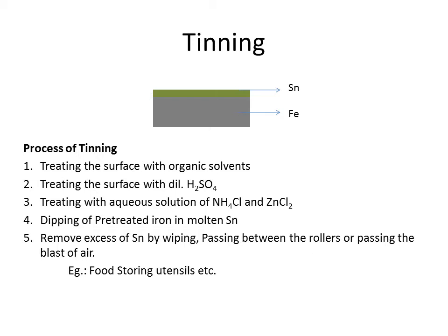Interestingly, since the coating metal acts as cathode, it will not allow the base metal to get exposed to the environment. As long as the coating metal is there, nothing will happen to the base metal. This is the principle behind cathodic metal coating.